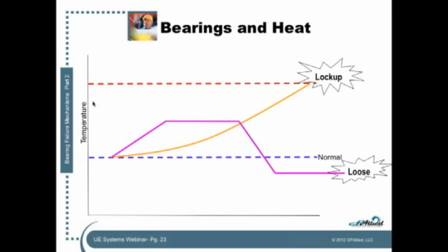So the fatigue failure has created spalling. The spalling propagates around the inner and outer race. Material is continuously removed from the inner and outer race as the spalling gets worse and worse and worse. So as material is removed, the internal clearances of the bearing are loosening up. So if the bearing were to heat up more, it's got more room to expand now, right? Because it has more room to expand, it really doesn't heat up. It just continually eats itself away and it loosens up, right?